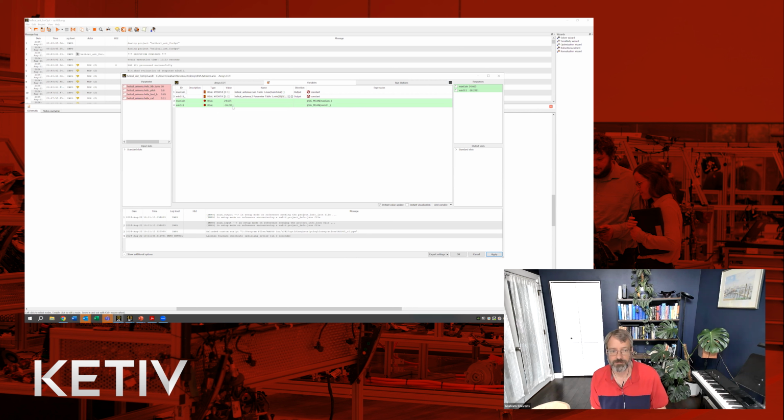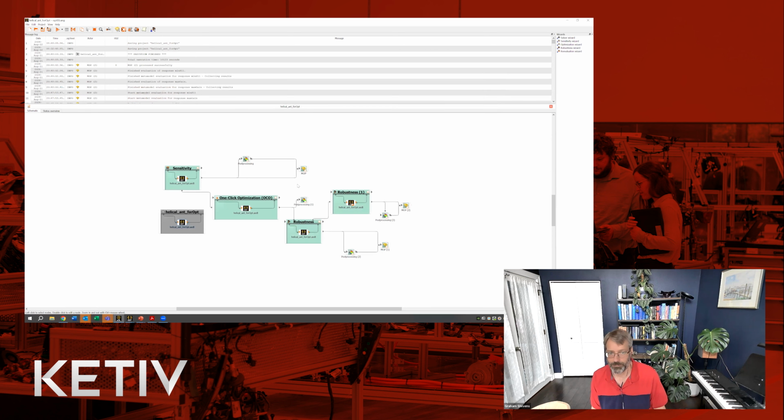And so I've added some variables here called max gain and min S11, and just grabbed the mean off of that table for each one of these, and then taken these variables and plunked them over here in the response side, so that we now have our input variables of the 4 variables that were in the original model, and now our output variables here all set up. And then on the run side, we have again our maximum number of iterations in parallel. And so that's how this sub-block is set up.